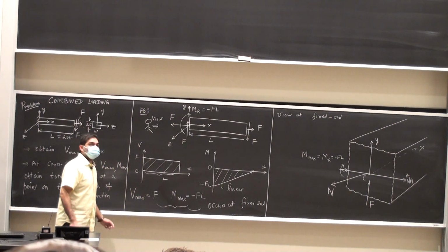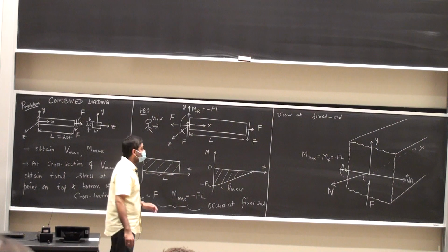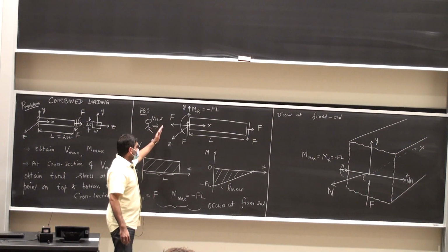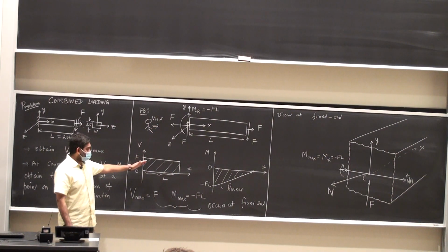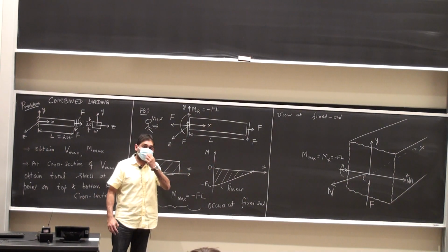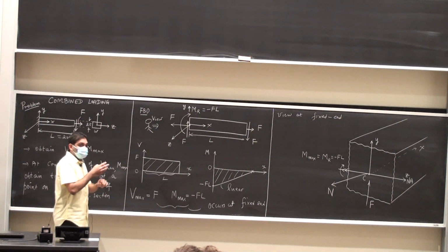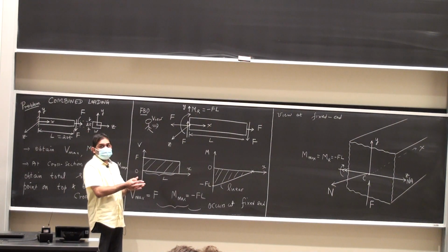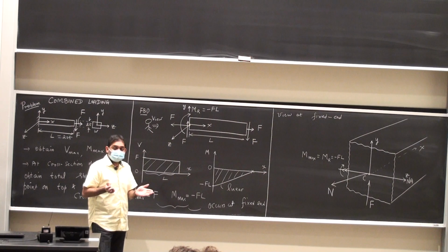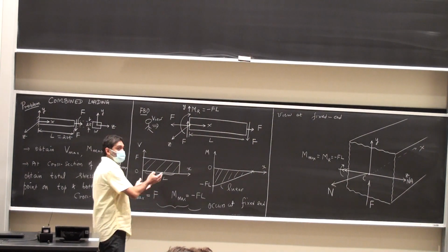So these kinds of figures are a must, which is why I don't want to have these on the current midterm exam and so on. You figure out what the support reactions are, draw the shear force and bending moment. This problem alone might take an hour in a final exam, because you're going to do this in 3 dimensions. But this is how reality is. If you're looking at a pipe that is bending and you want to understand what are the stresses that cause it to break, this is exactly what you're going to be doing.